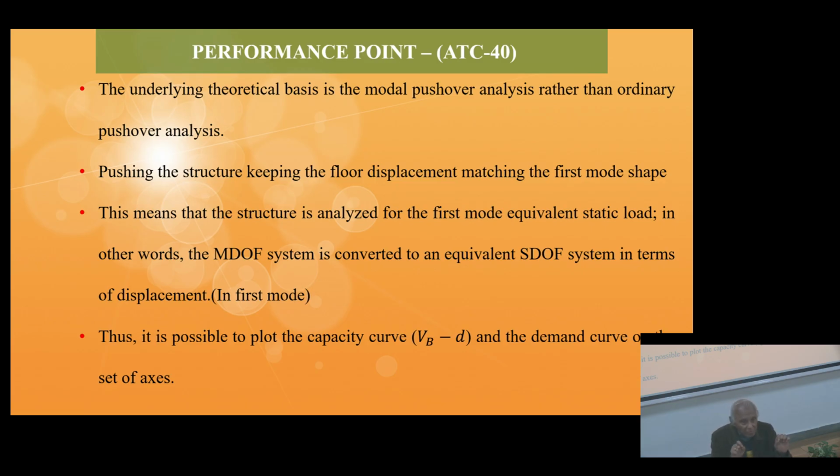You must have Chopra's book or any other textbook; in my lecture notes also I have shown you that say I have a beam. I want to convert it into a single degree of freedom system. So I convert it into a single degree of freedom system by considering at the center, I lump the entire mass of the beam and ask what is the force necessary to push by unity the center of the beam.